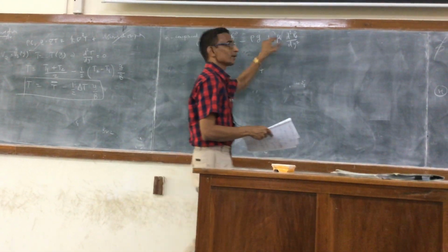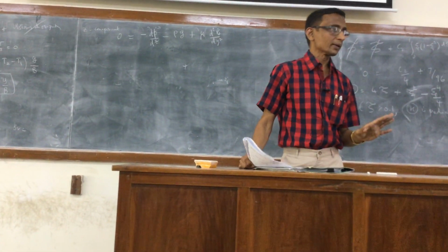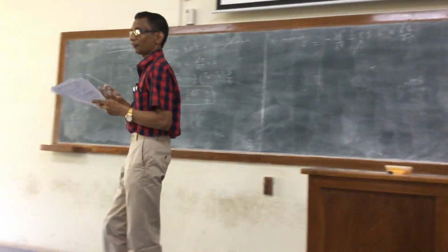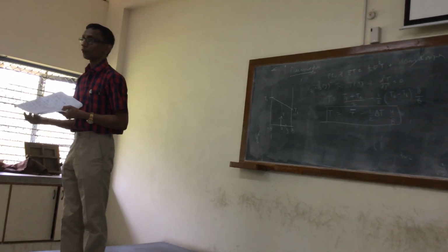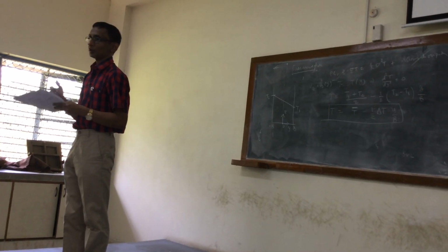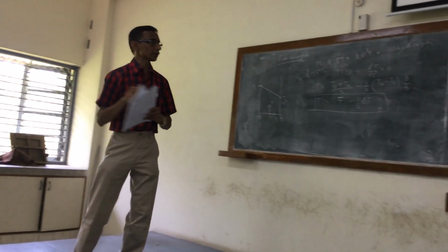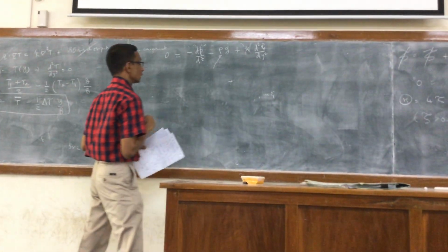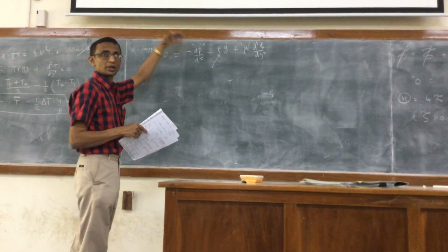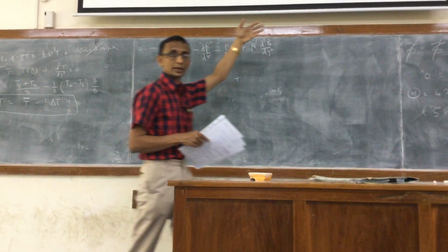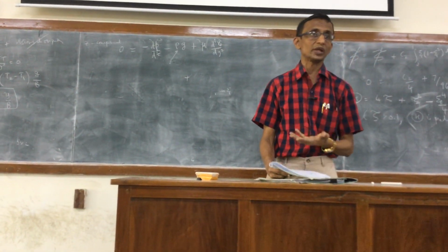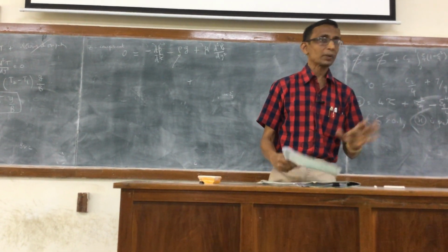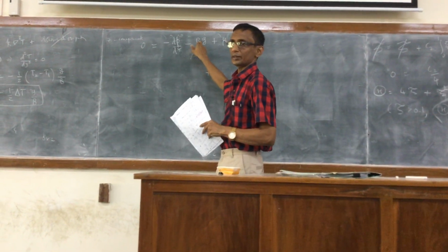We have said that the viscosity dependence on temperature is neglected. So the temperature effect is coming because now the density, to capture the minimal effect of the temperature, you have to account for the effect of temperature on the density. This is probably regarded as a compressible fluid, right, in this sense. Now, of course, if you allow the density to change, then you have to think about the continuity equation, because the continuity equation will no longer be just the divergence of V equal to 0. But that is not what is being done. That is being retained, and the temperature effect on the density is considered only in this equation.